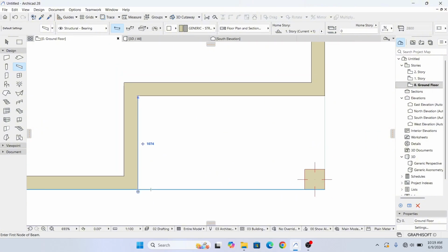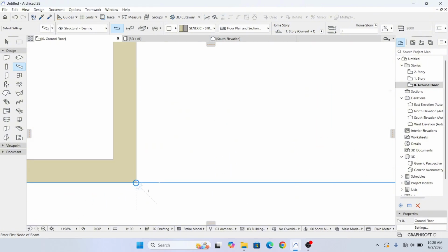Now this is where our beam is going to be. Don't forget, I told you our beam is going to sit on top of the column. The beam is going to transfer the roof load from this angle to this angle, and it's going to sit on top of this column. Don't forget, inasmuch as you're an architect or a designer who is designing for aesthetics, you're also going to design for structural standings. Don't neglect that, please.